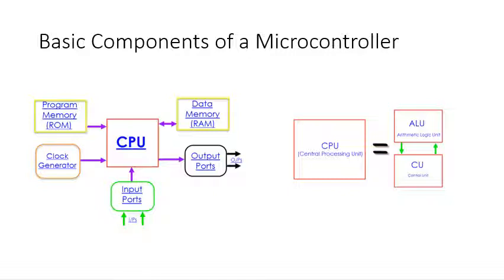Input and output ports provide the microcontroller a physical connection to the outside world. Input port provides a gateway for passing on the data from the outside world with the help of sensors. The data from the input port is manipulated and will determine the data on the output port. Output ports allow the microcontroller to control external devices. Generally, all ports in a microcontroller have dual functionalities. That is, they can act as both input and output port, though not as the same type at the same time.